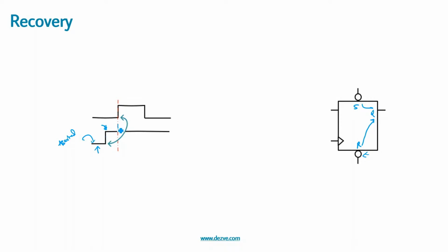So recovery time is the time between the deassertion of a reset and the assertion of the active clock edge. These recovery and removal times are specified in the Liberty file for all the asynchronous inputs.